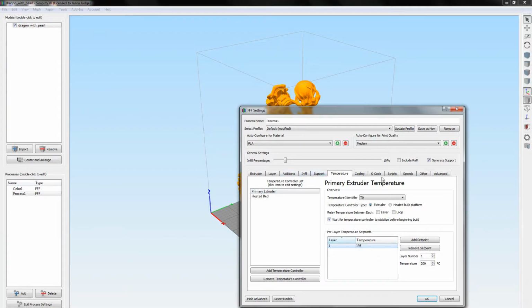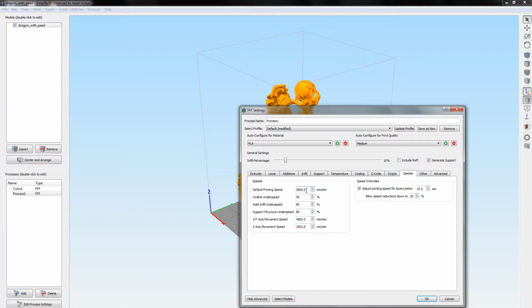Next, we've got the print speed. This is how fast your printer will be laying down the filament onto your print. Most people refer to these values in millimeters per second, like 60 millimeters per second, but your slicer might default the display to millimeters per minute. So 60 millimeters per second would translate into 3600 millimeters per minute. And 60 millimeters per second is kind of the ideal setting, but just keep that in mind when you're setting these parameters.